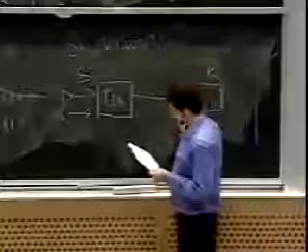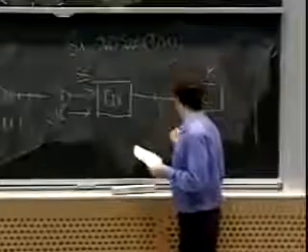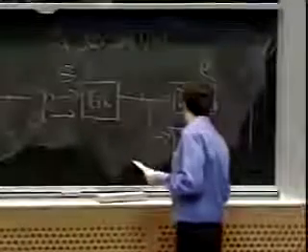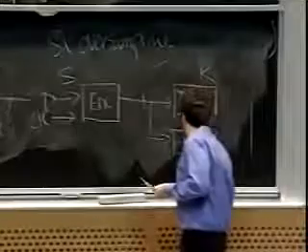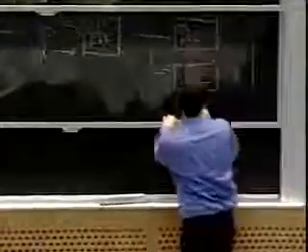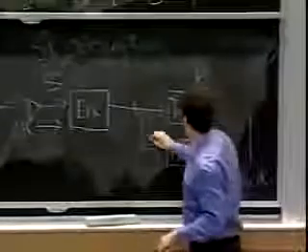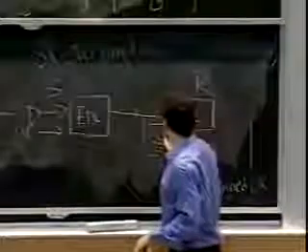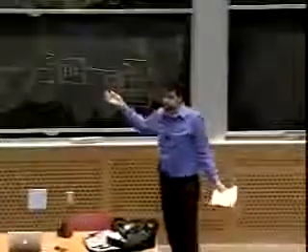So what we're going to do is use our phase lock loop to do that. The phase lock loop is going to take in the incoming signal as well as the unaligned clock from the local machine, and it's going to input into the decoder an aligned clock signal. Basically, this PLL is going to be able to reconstruct the clock signal from the sender. Of course, it takes a little bit of time for the PLL to reconstruct the clock signal.